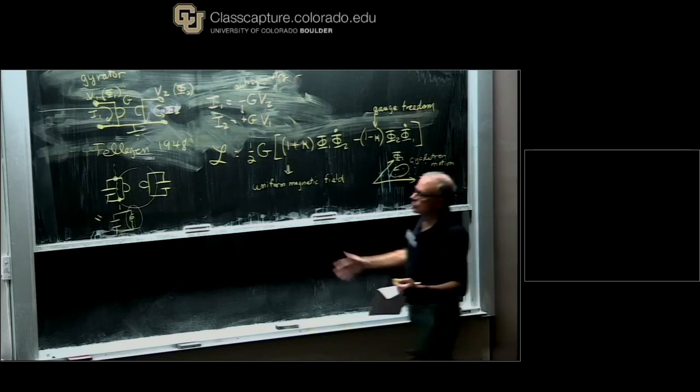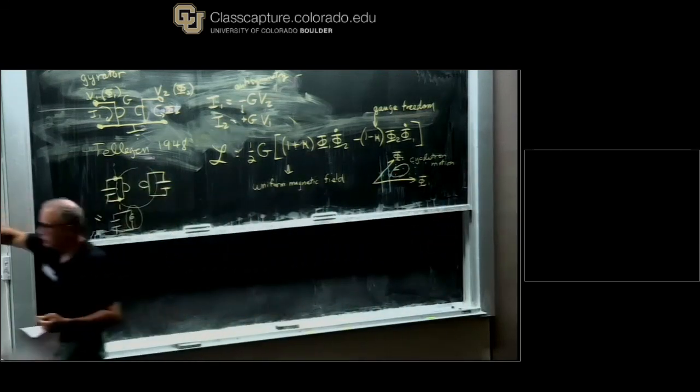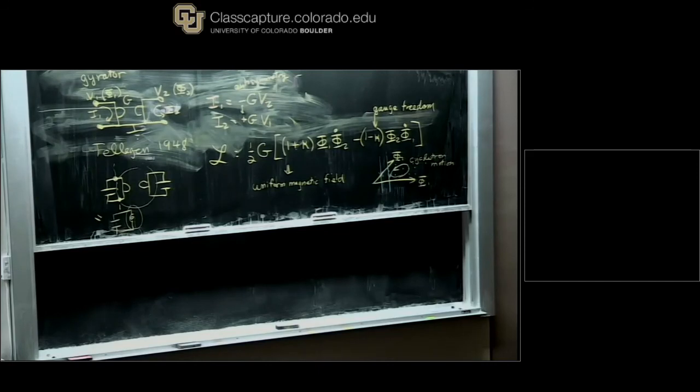The other comment is that there are passive circulators. They're in very common use, except they only work in certain bands. So it is very much an idealization to say that it has a certain scattering property independent of frequency. We'd love to have such devices, but we don't. Real devices are networks of ideal circulators or gyrators and regular inductors and capacitors, which describe the actual frequency dependence.